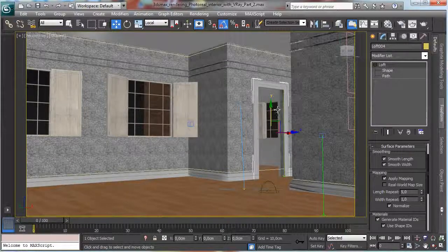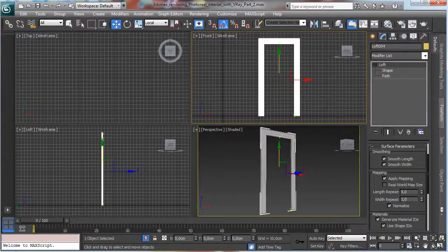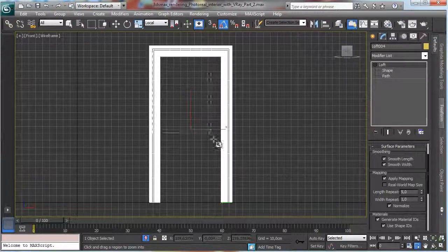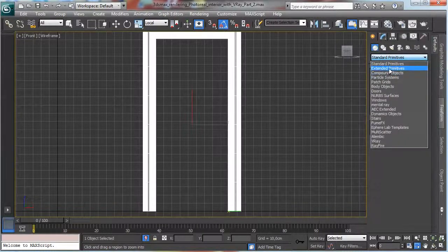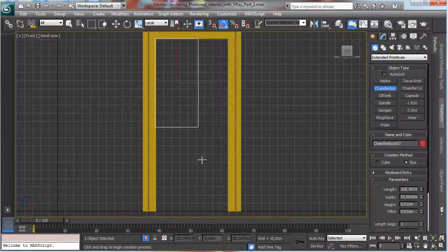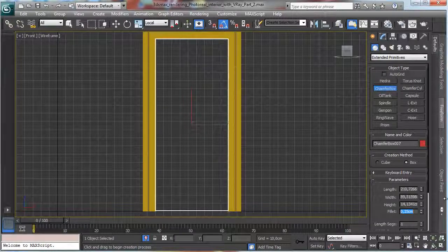and then we have just to add a door, and the door actually can be really simple. So let's go in the isolation, and we make, let's say, an extended chamfer box, and let's use something like that. Okay, the chamfer will be 25, the door is 14 centimeters, it's not a problem actually, and this one will be something simple.